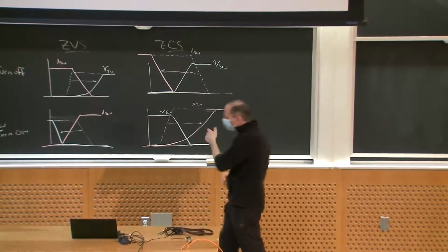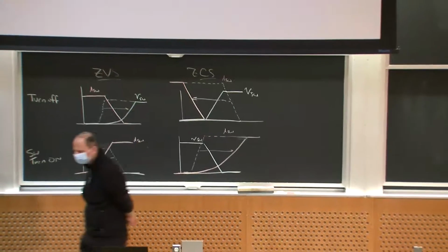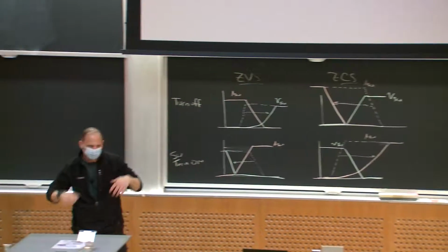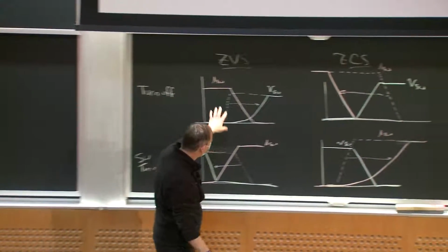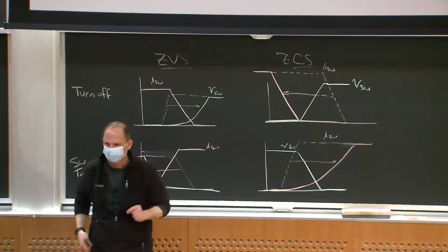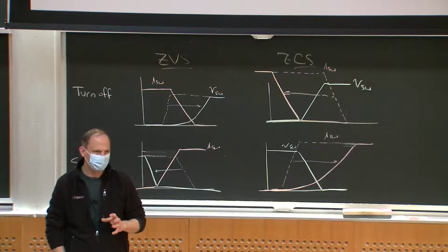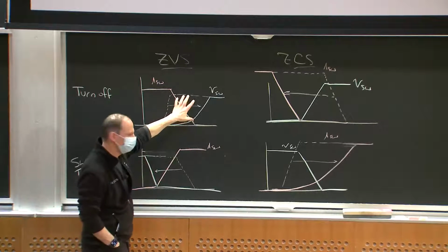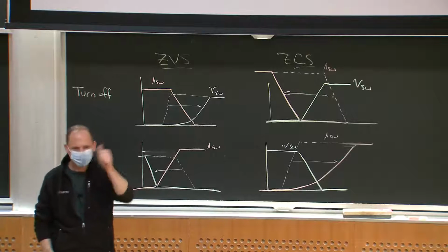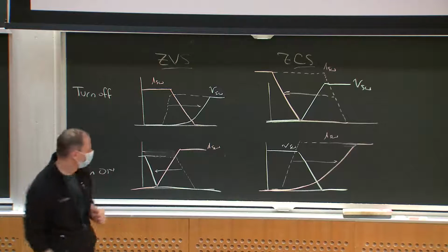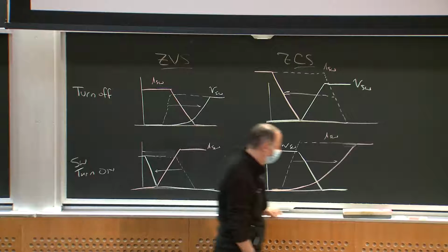Okay, so what do I get out of soft switching? Soft switching is sort of implied: if I'm snubbing the switch transition, I'm doing it in a pseudo-lossless fashion, meaning if I put a capacitor across the device for the turn-off loss, I'm going to recover that energy. So one thing I can get out of it is I reduce the switching loss.